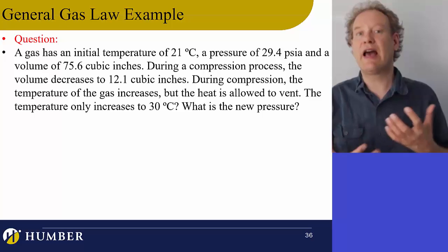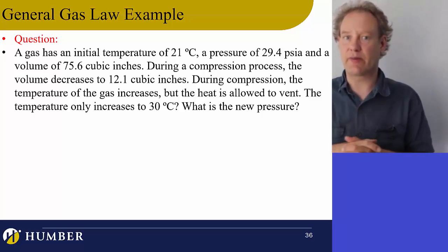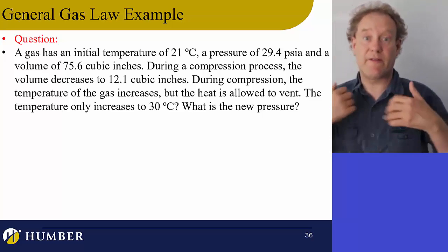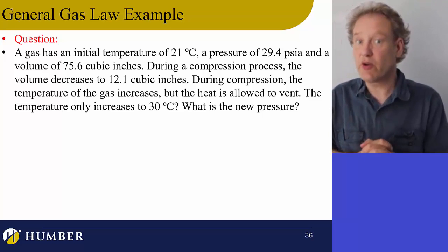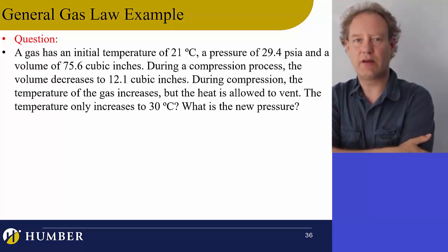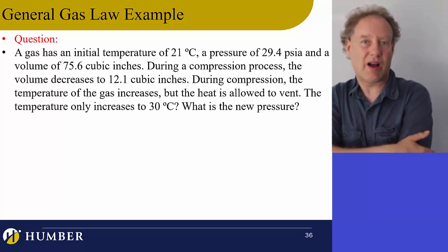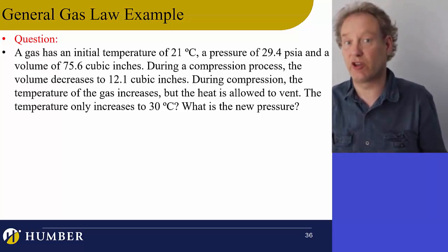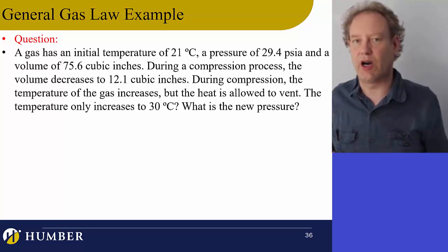So that's really how a lot of the heat leaves a compressor, because a compressor has fins on it, and air is going over it, and we could put a fan over it. Actually, a lot of compressors do have fans over them to remove that heat. But why do we want to remove the heat? I mean, what's wrong with some hot gas? We can still put hot gas into pneumatic actuators. It's not a problem. They still work. As long as it's not super hot, it's not going to damage them.